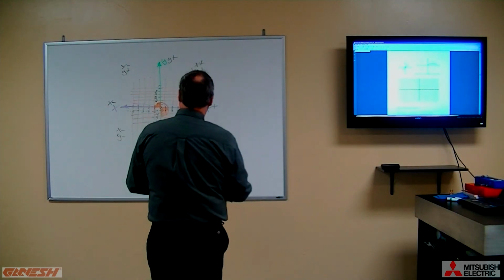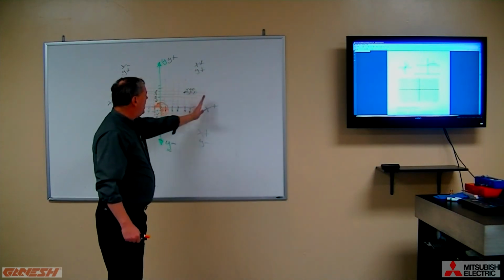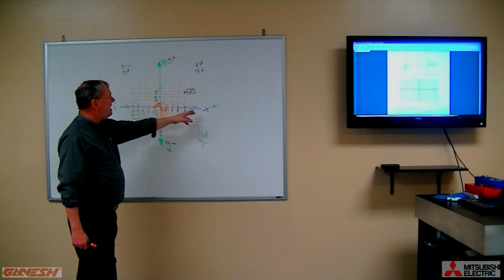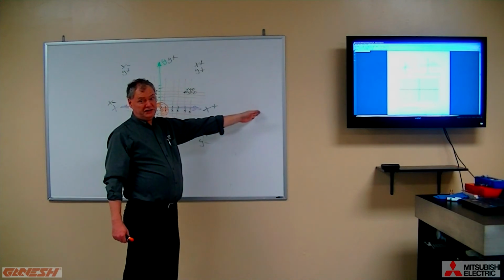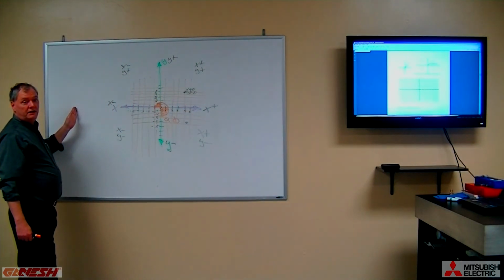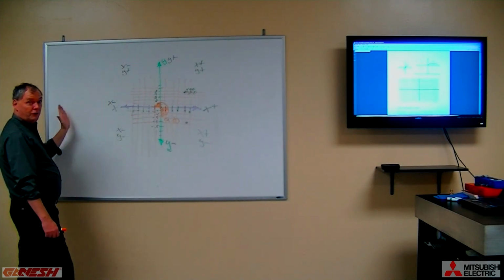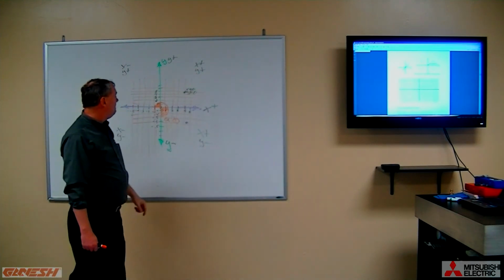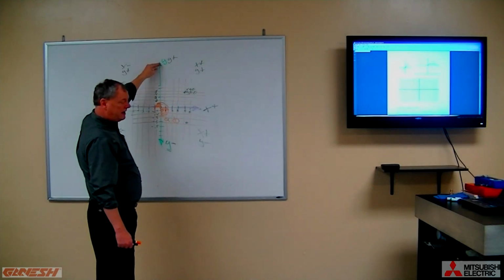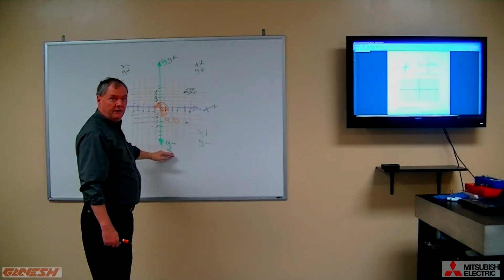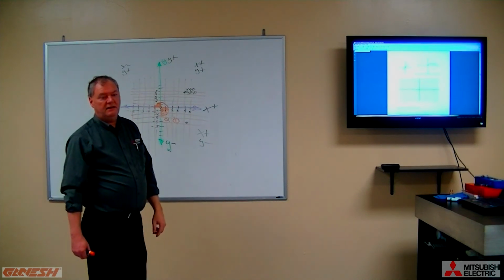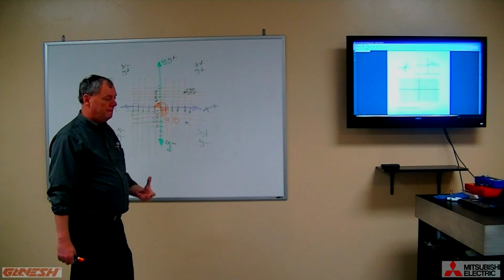Our table has travel limits, so we can say that from the center, our table might be able to move 20 inches in x all the way to minus 20 in x. So it would be said to have 40 inches of travel. And then likewise in the y-axis, it might be able to move from y10 to y minus 10. So it's said to have potentially 20 inches of travel.